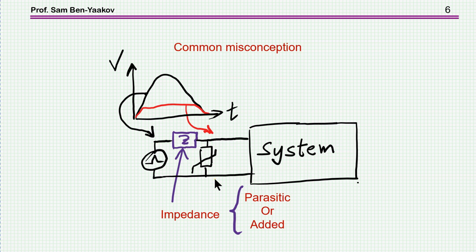So any protection unit is actually relying on a voltage divider, not just clamping it, but actually dividing the voltage. There is always a series element that is controlling the current. In fact, the way to test the protection according to the regulation is to have a voltage source in series with an internal resistance, which is limiting the current to whatever given value is required by the regulation.